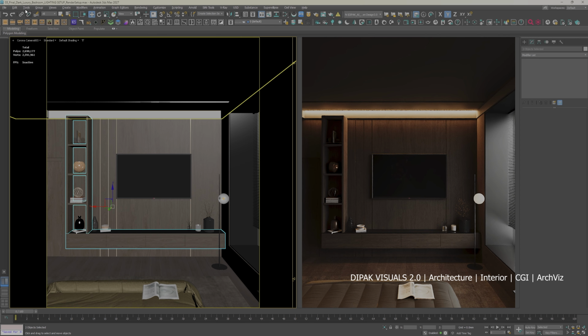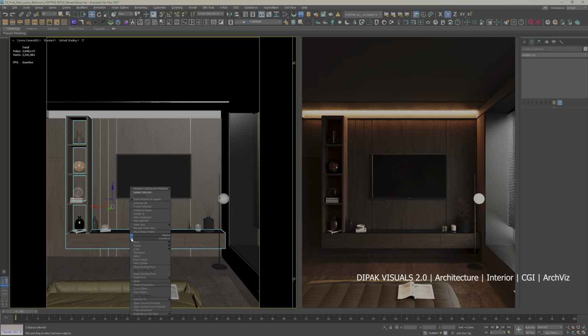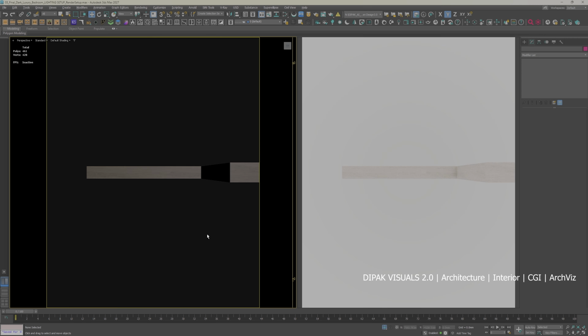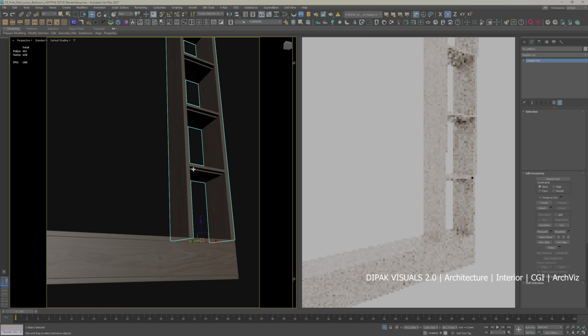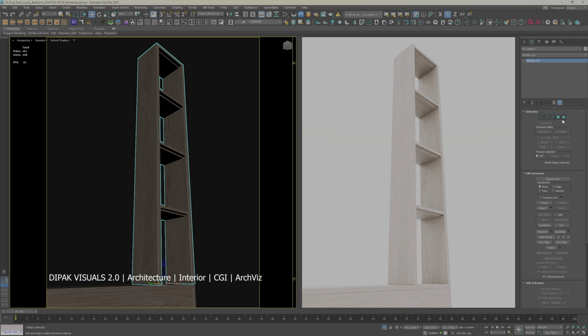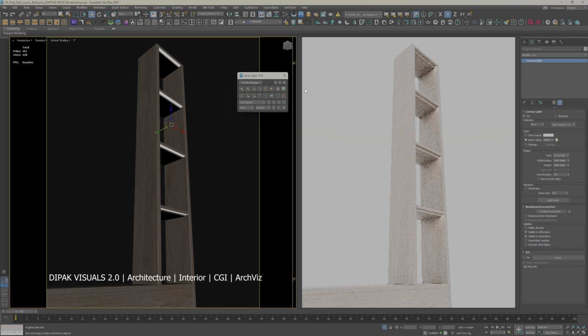Using Autolight, I quickly set up lighting for the headboard, accent light, TV unit, display shelf, and cabinet. I also use it to create wall cabinet lighting, open shelf lighting, and inner shelving lighting with just a few clicks.